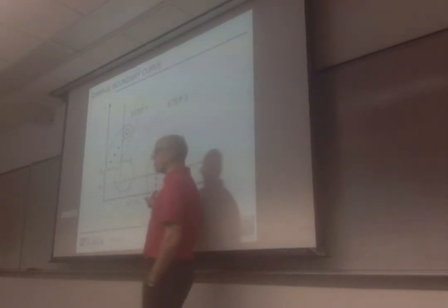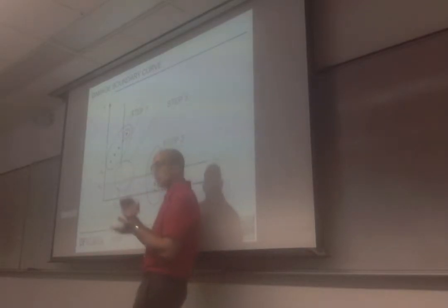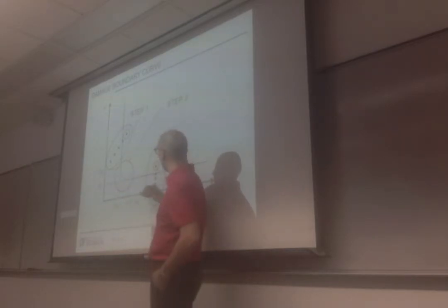So the area under the curve is the same, it's just now going to get higher and higher, because if the cushion is stiffer or if there's more pressure in the cylinder, instead of compressing and having that velocity change happen over a long period of time, it's going to happen in a shorter and shorter time. So you have larger and larger acceleration as you go up.